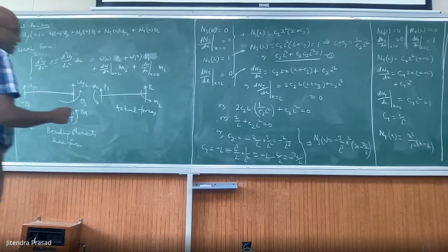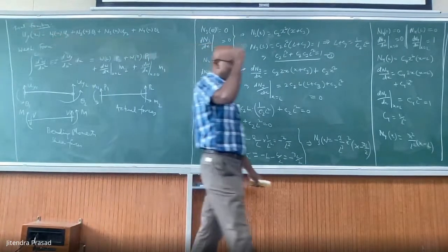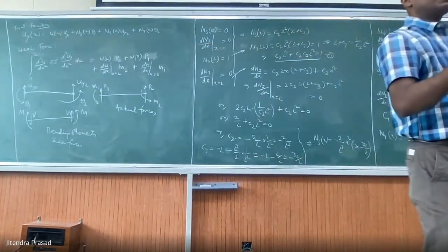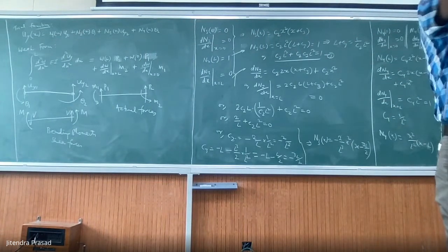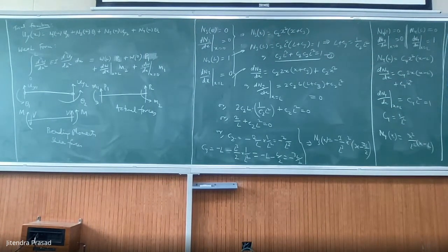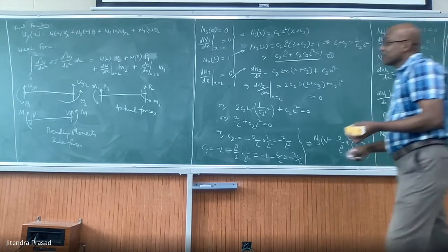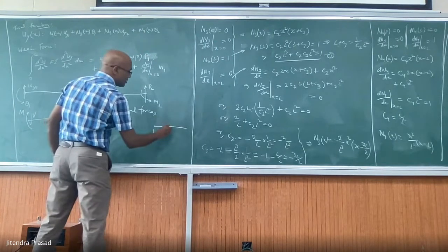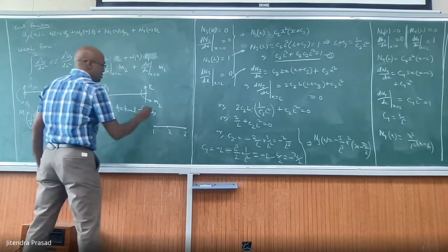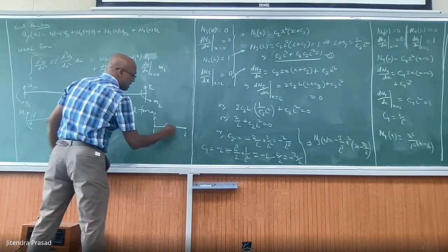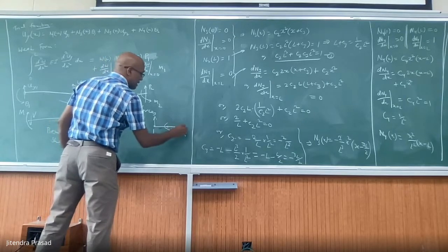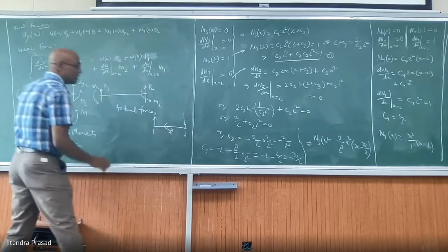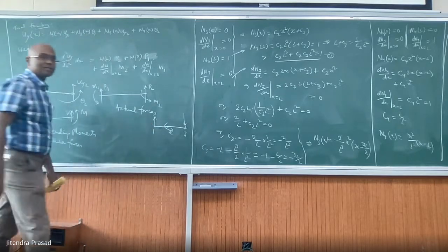Always remember that when you are solving an elasticity problem, finally in your force vector, actual forces appear. You have to forget what is the bending moment there, what is the shear force. You are looking at that point, seeing what is the force there. So let us say you have a beam, node 1, node 2, node 3, and you have forces like this, and like this, and nothing else.